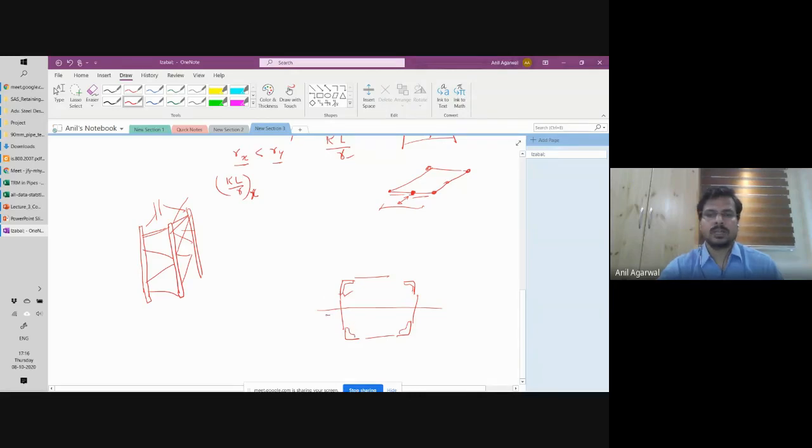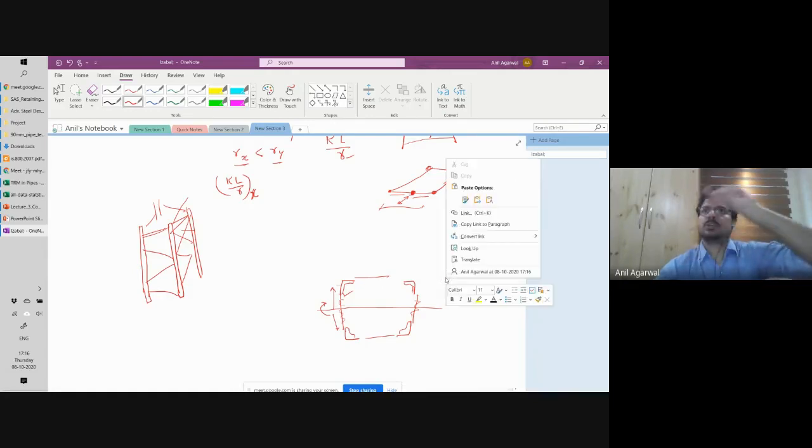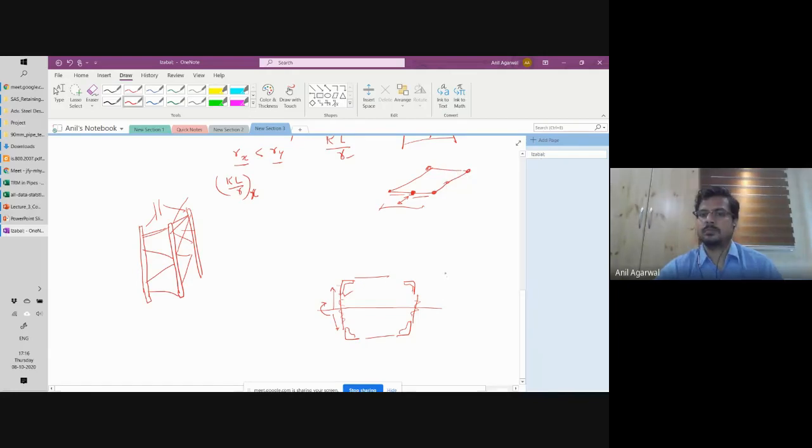So when the buckling takes place about this neutral axis or bending takes place, the stresses or strains at each location will not be exactly proportional to the distance from the neutral axis. Okay, and the reason for that is that these bracings are weak; they are not very stiff. Okay, and as a consequence, you will not have linearly varying strains. So because of that, your deformations will be larger than what your assumption of elastic beam theory presents.